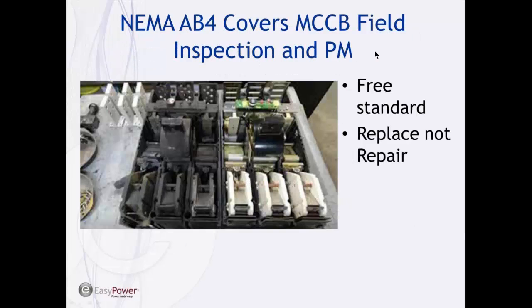So I mentioned this NEMA AB4 standard, and it does cover field inspection and preventive maintenance of breakers in the field. I believe that's still a free download if you go to the NEMA website. It's going to basically tell you when to replace the breaker, not anything about repairing them, because they don't consider molded case breakers to be repairable. So if there's an issue with the breaker, you just buy a new one.